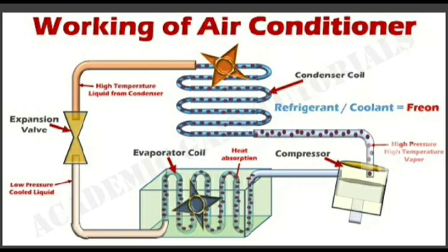Now, at the first step, the compressor starts working. The job of the compressor is to pressurize or compress the refrigerant Freon, and we know that if pressure increases, it also increases the temperature. So, when the compressor compresses the refrigerant Freon in its gaseous state by squeezing the gas very tightly together, it will heat up. We heat up the refrigerant in order to get its temperature higher than the outdoor temperature.